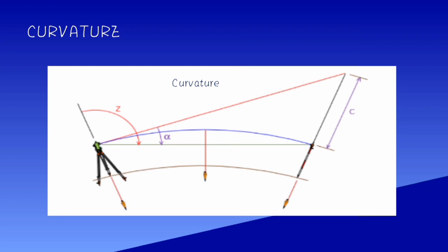It is perpendicular to gravity at the instrument location. The green line is the new line of sight between the instrument and the target. It is perpendicular to the gravity only at its midpoint. And the blue line is at a constant height above the reference surface and perpendicular to the gravity along its entire length, making it a curve.